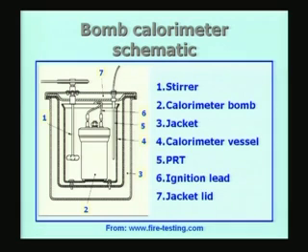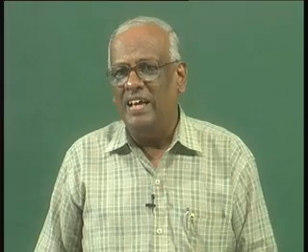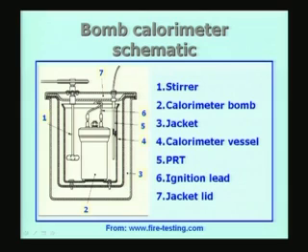This water will saturate the oxygen, and therefore whatever water is formed as part of the combustion process is going to condense, and therefore it is not in the form of vapor. That is the idea with which it is done. Therefore, we will get the so-called higher heating value by using the bomb calorimeter. So, the experiment is very simple.